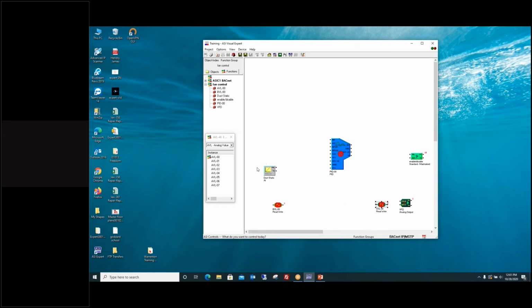That's fine. Okay, so enable all of the icons that have the red circle. You can either do it individually or select all. You can just select enable there. If you're going to do select all, you have to right click where there's nothing. So we're going to get rid of the red circles. Do that on the PID itself. The PID still has the red circle on it.